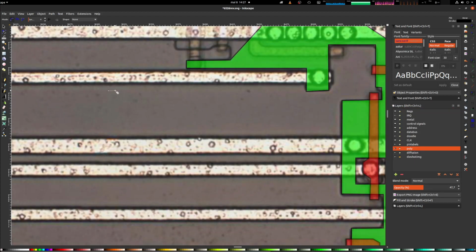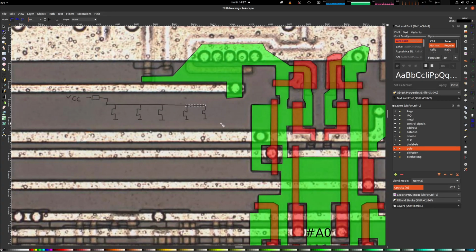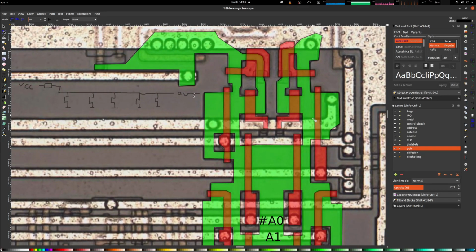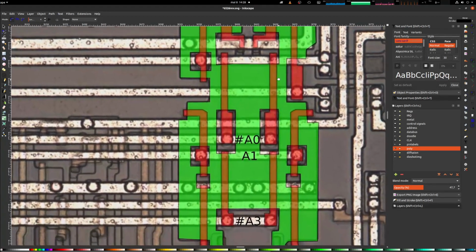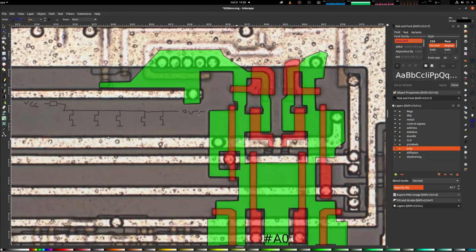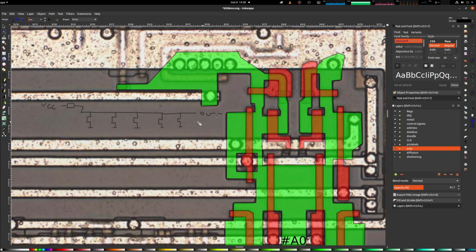You have the pull-up to VCC, and then you have a wired OR configuration. So you have one transistor here, goes down to ground. I believe you have 5 of those. Let's see what they are connected to. So this will be the output. You see you have another one on this side, which is very, very equal. We'll come back to that shortly.